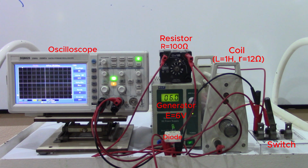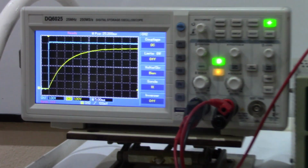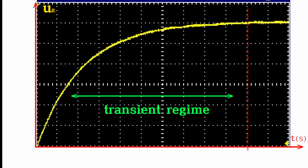For example, here we have a coil with a small internal resistance r equals 12 ohms, and an inductance L equal to 1 Henry. A generator terminal voltage of 6 volts and resistor resistance equal to 100 ohms. There is a transient regime in which I increases until it reaches a constant value, I max. We have then reached the steady state, where I remains constant, equal to I max.